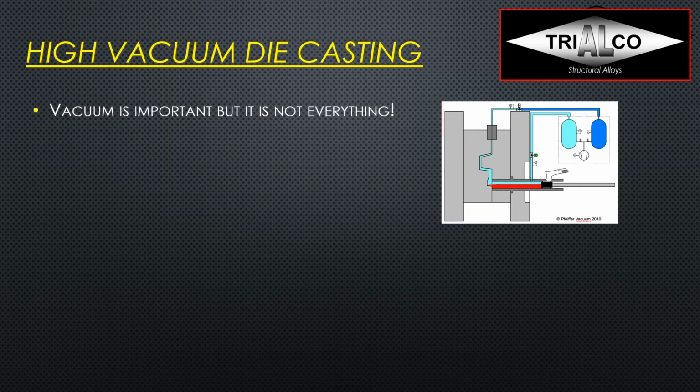In any case, vacuum alone is not everything. It's the same thing with the alloy. You can get the greatest alloy if you screw up the melting practices or handling practices. You can screw up everything. Here again, you can have the greatest metal and the perfect vacuum, and you can still not get good properties. So on top of vacuum, you need special alloys. The right alloys that have a higher purity than the typical A380, you need tighter tolerances, which doesn't mean that they have to be just primary, and that you can't recycle internally and things like that. These are all myths, and are talked about more in other webinars in this series.